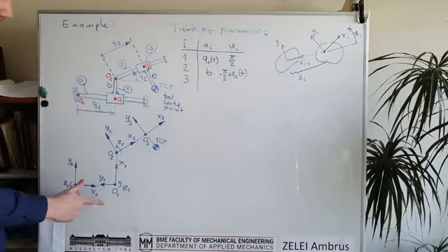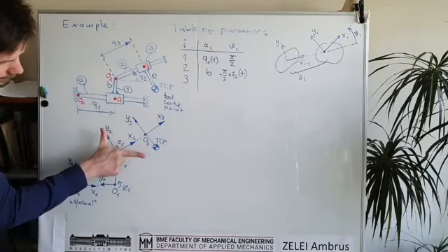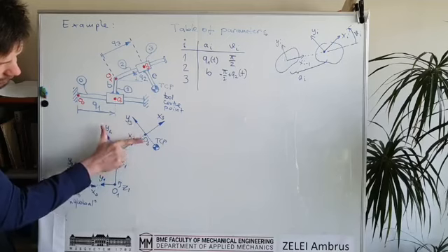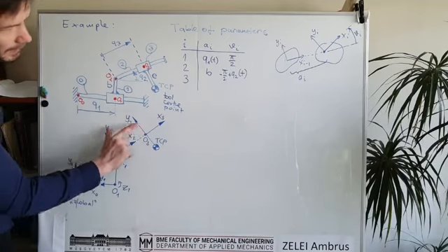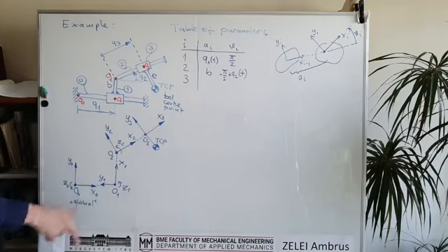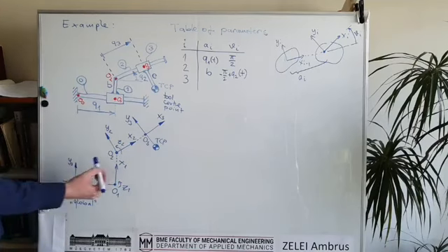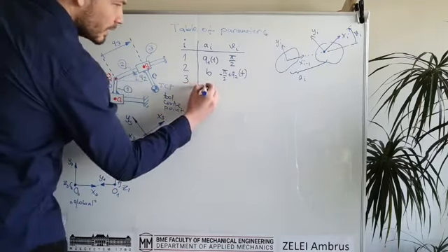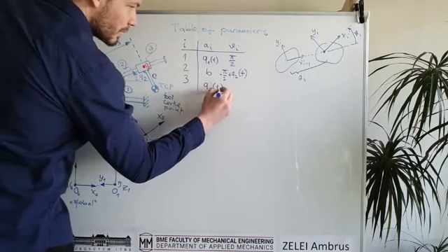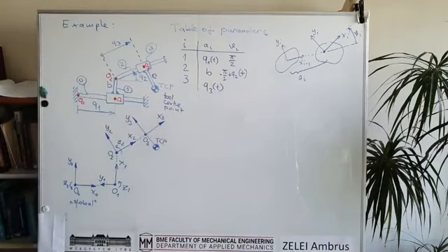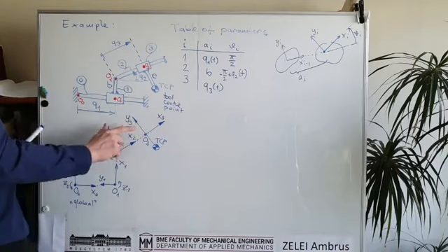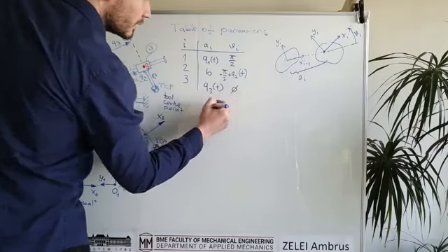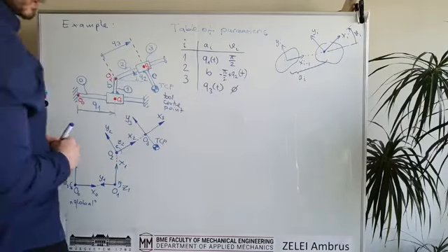So first we go here and then we go here, and then we can have a time dependent rotation angle additional to the minus 90 degrees. And then in the third transformation we go from here to here. This distance is Q3. So the third joint parameter, which is time dependent, is here, and we don't have any rotation between these two coordinate systems.